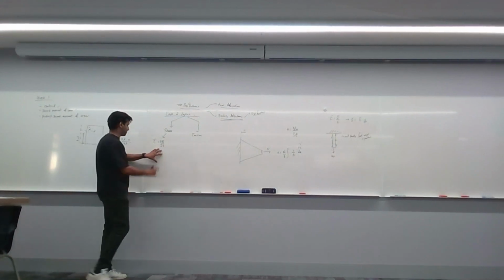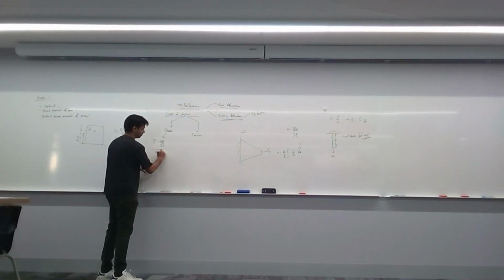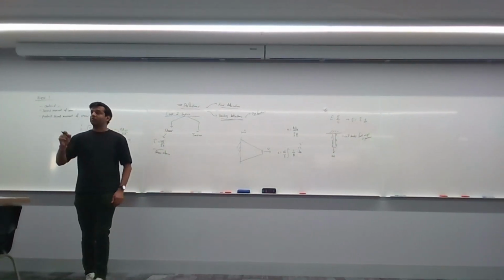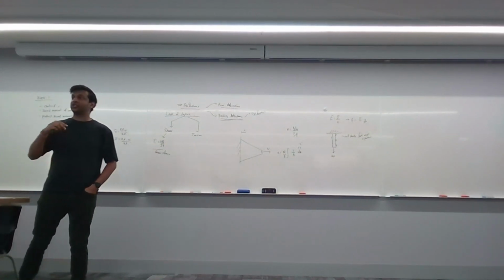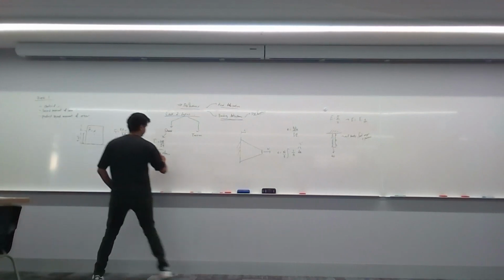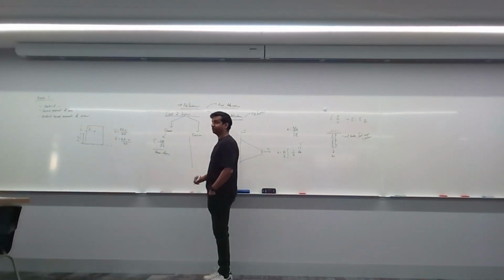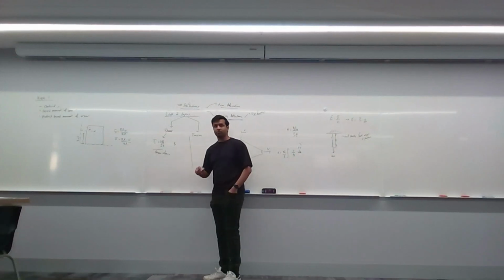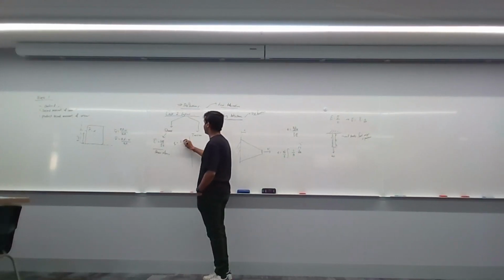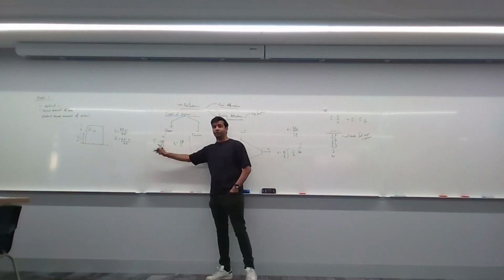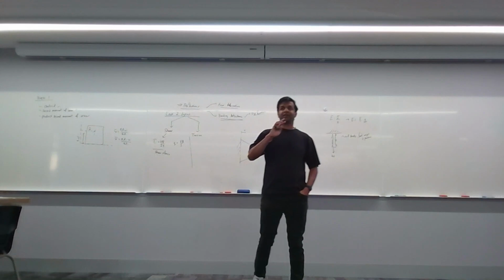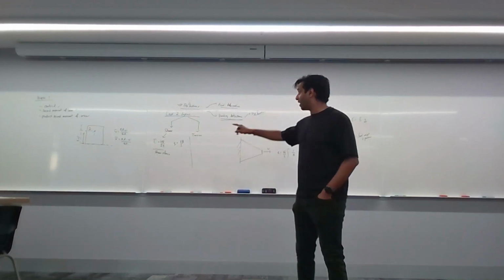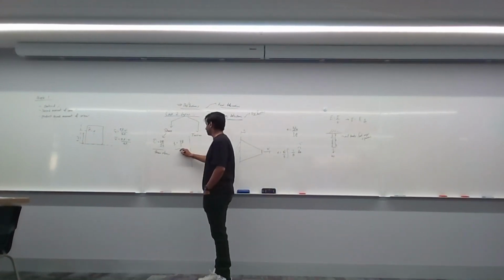This is the formula for shear stress. Now, there is something else that's known as shear flow, right? Shear flow has a similar formula. It's usually denoted as q, and shear flow is VQ over I. Almost the same formula as this, except there's no t, right? But it is quite easy to misconstrue what shear flow actually means. Shear flow.